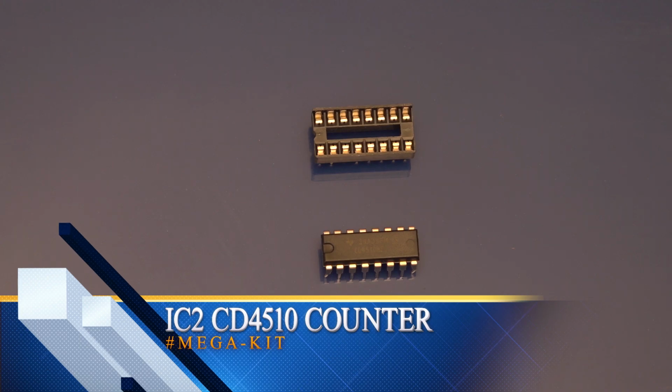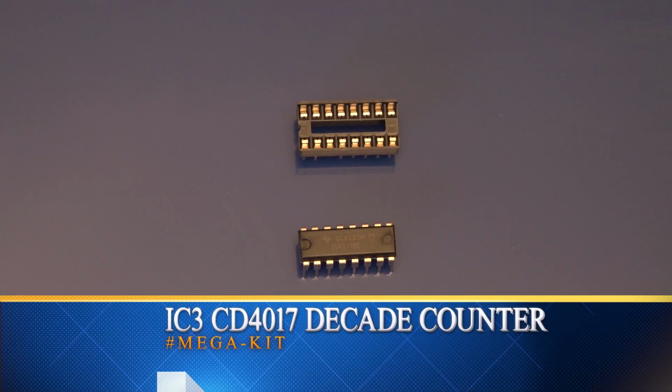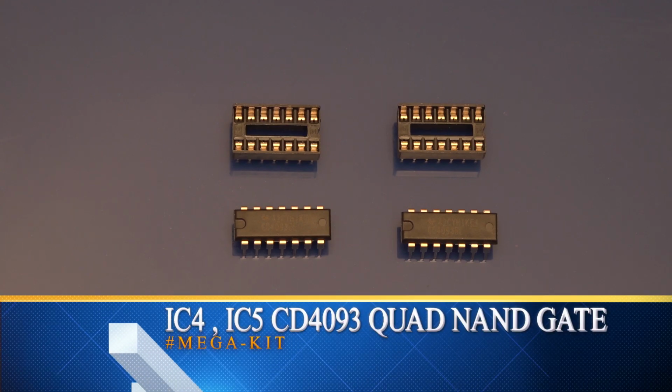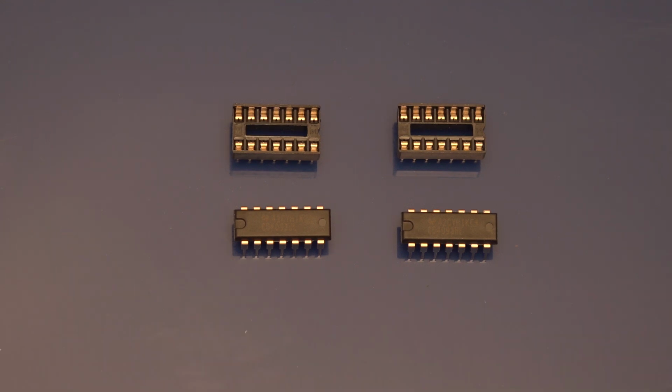IC2 CD4510 counter, quantity 1 number with socket. IC3 CD4017 decade counter, quantity 1 number with socket. IC4, IC5 CD4093 quad NAND gate, quantity 2 number with socket.